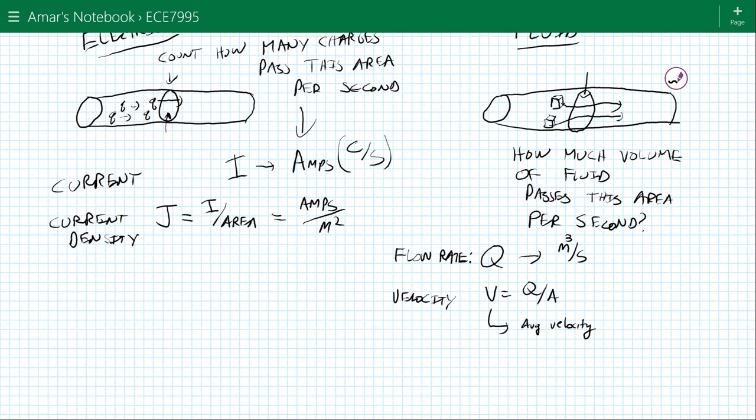Similarly, let's say you have two very wide pieces of wire, and somewhere that wire gets damaged, and for some reason the wire diameter there is much smaller, what's going to happen there? The current density there is going to be much larger. So what I'm drawing here is, let's suppose we had current running through a pipe, and there's two very wide sections of pipe, and then in the middle you just have this narrow section here.